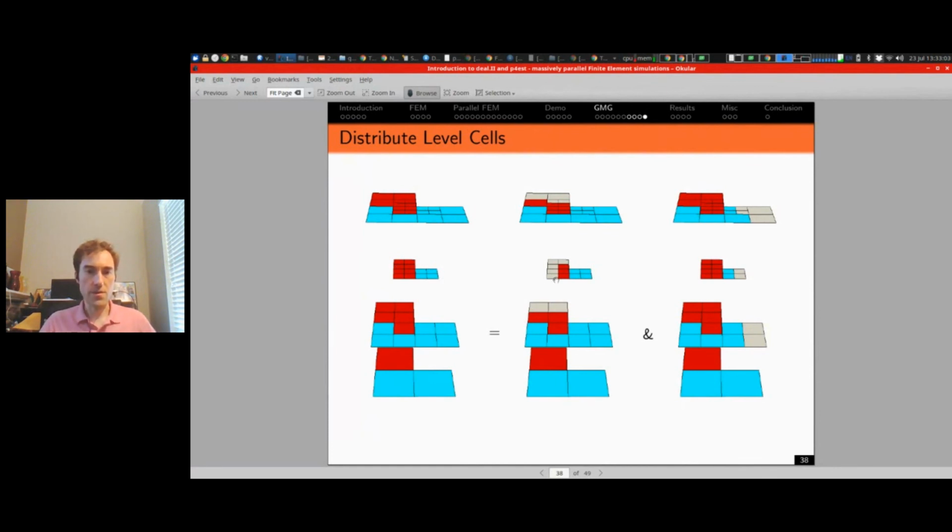And I know, for example, how the storage is done in deal.II for this example here. The triangulation is the whole object, and it stores the different kinds of things, for example, the ownership of a cell or the vertices of a cell, in separate structures, and they are grouped by level, and then over the objects. So it is not one array of structures, but it is structures of arrays where appropriate. And this also allows us to pack cells very efficiently. All cells on one level are in a contiguous memory range in one allocation. And I just know how to jump between the cells based on very little information.